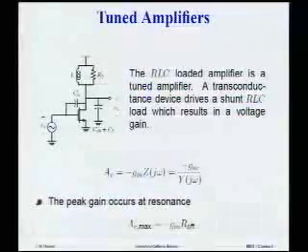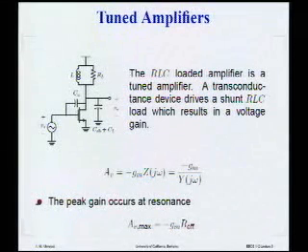So what are some of the possible benefits that we're getting from this inductor? Well, just naively, it looks like we can operate this transistor at any frequency we want, right? No matter how much capacitance we have in this amplifier, we can always put an inductor there to tune out that capacitance and have a resistive load at the frequency that we desire. So it looks like we can take this amplifier, which maybe had a 3 dB frequency of 100 megahertz, and now operate it at gigahertz. Okay? We'll come back to that.